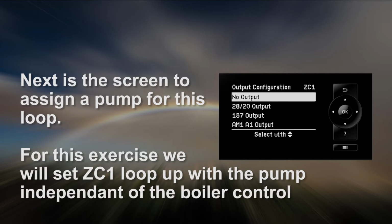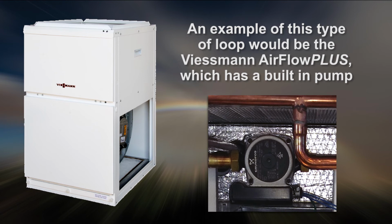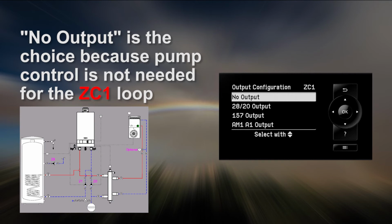For this exercise, we will set zone circuit 1 loop up with the pump independent of the boiler control. An example of this type of a loop would be the Viessmann Airflow Plus, which has a built-in pump. No output is the choice because pump control is not needed for the Zone Circuit 1 loop.